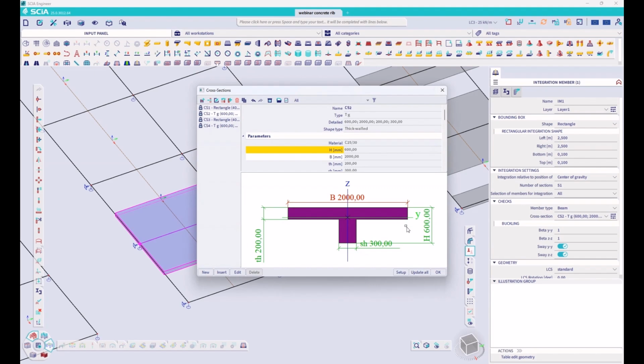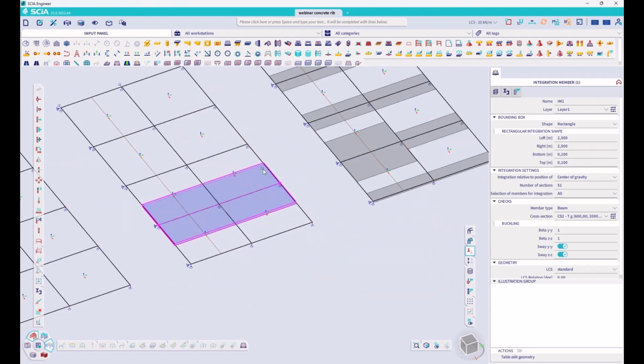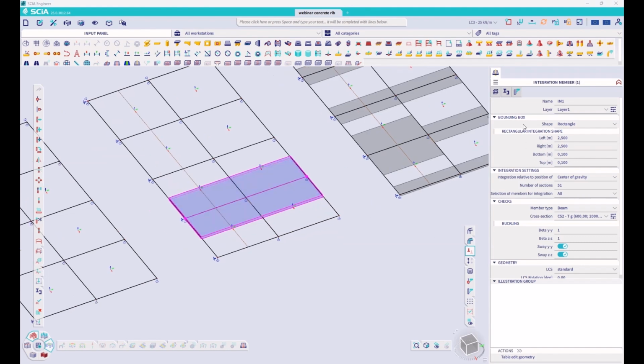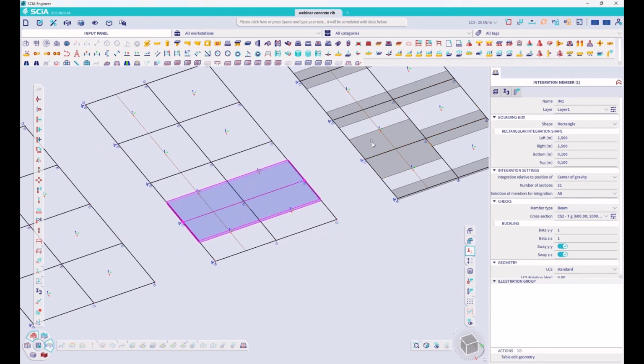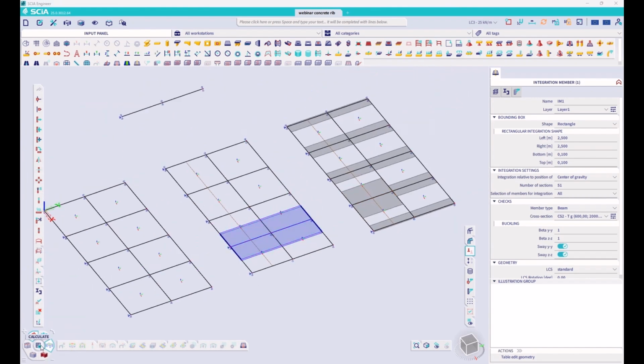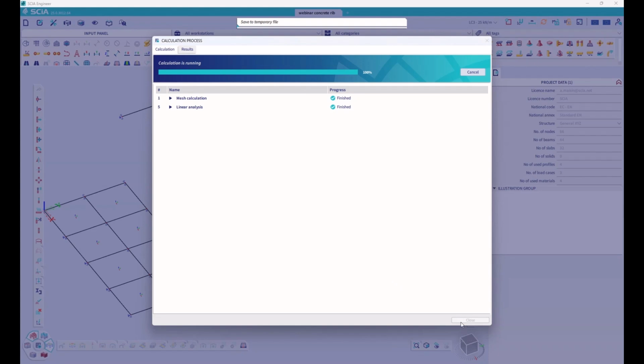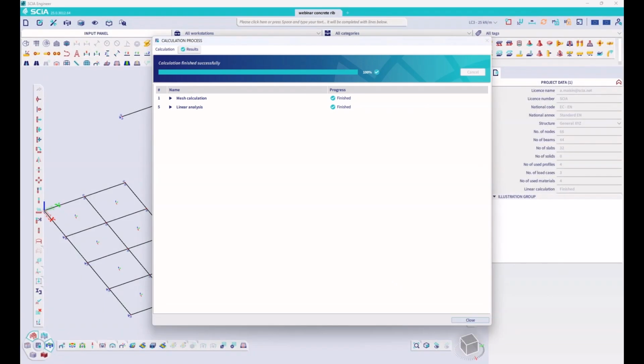So in this case, I'm actually integrating the forces over a larger width. But once I run the reinforcement design, it's going to take a smaller T-section. And in this case, I should get really close to the actual 1D member, since at this point, I'm integrating over almost the whole width. Although due to some 3D effects, I'm probably still going to have some normal force in the ribs with the plate compared to the 1D model. But for the moment force, I'm guessing that the results will be very similar to each other.